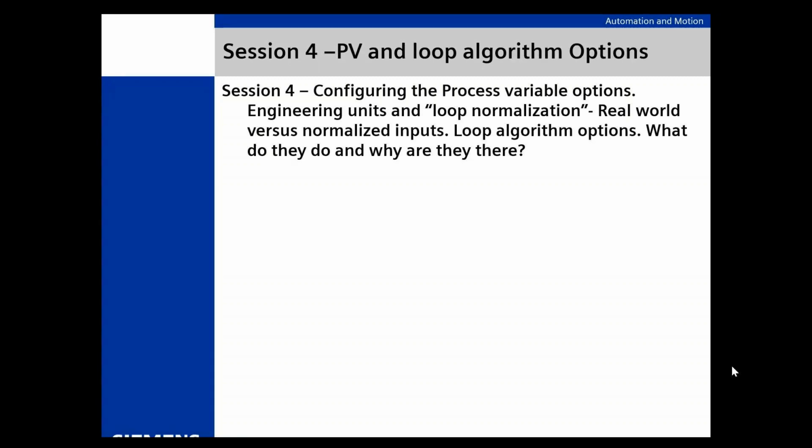And that's where things in the control business get a little fuzzy, okay? Because people say, well, I'll push the auto-tune button and that'll be great. Well, good, sometimes, not all the time. And the more complexity you have in this control loop, the less that's going to be so, okay? That's just the way it is. I don't want to scare anybody, but I'm just saying, don't expect to always push auto-tune and have it auto-tune and walk away. And we're going to go into some of those other things in just a second.